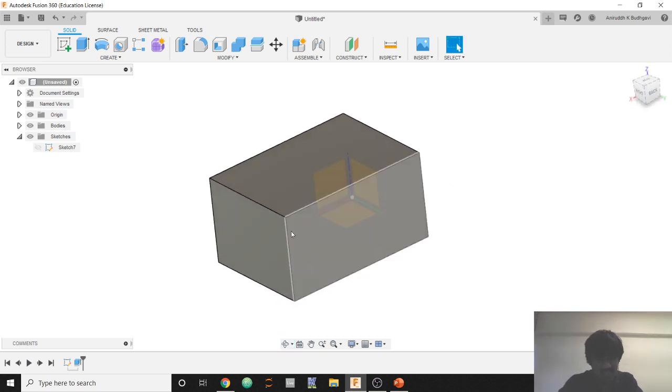What I'm saying here is that when I'm 3D printing, these vertical sharp edges here can cause a bit of a problem, because when the 3D printer is going, it is going in one direction and then it has to suddenly change direction again. So it's not smooth at all. So to avoid that problem, I have to make these edges rounded in nature. One way would have been to go back to the sketch, create tiny arcs everywhere, and then apply the extrude using that. But there is a different tool over here which is very easy to use. That is the fillet tool.